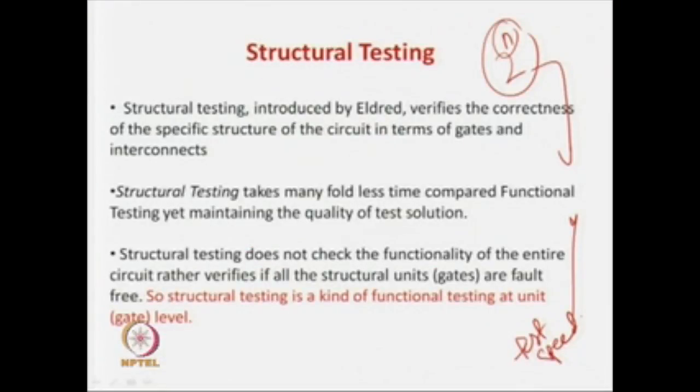But you can understand, you have to get the idea that if you have to test a chip at the terahertz level or even higher, the test equipment cost will be so high that you can never make a profit out of using the tester and testing the chip. So ATE, which we have shown in the last class, is very, very expensive equipment, and that is the main reason why we cannot take the test speed to gigahertz or terahertz or anything at that level.